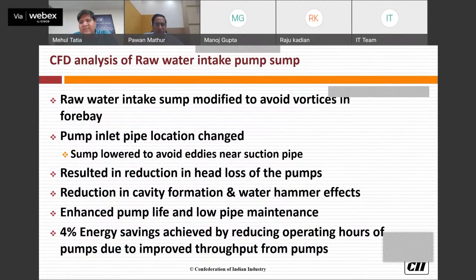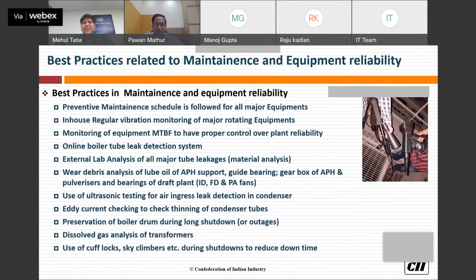That is also a good area, CFD in boiler combustion, your cooling water areas. Even if some of the plants are facing problems like boiler tube leakage, it could be one area which could help you evaluate why a particular zone is getting higher tube leakages or not.